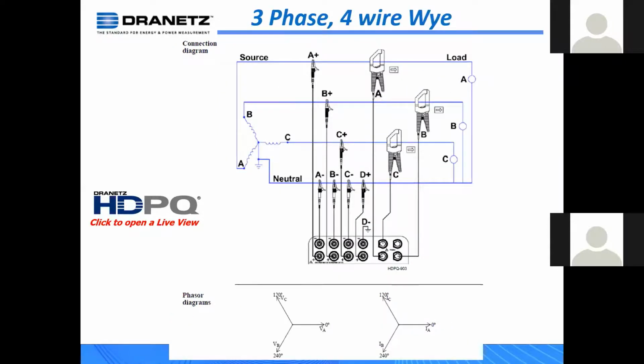So now we kick it up one more notch. We're looking at a 3-phase 4-wire Y. Okay, and by the way, what I've spoken about are the proper connections for energy and power quality for single phase, split phase, and also for 3-phase Y. So going back to Blondel, we have 4 wires. We need N-1 watt meters, so we need 3 watt meters, which means 3 CTs.